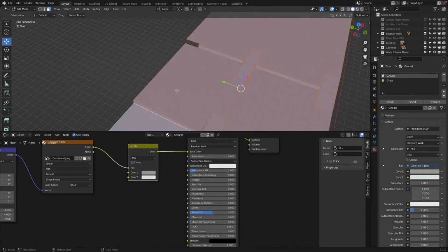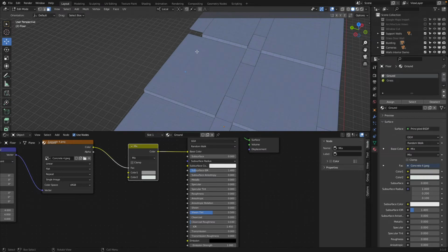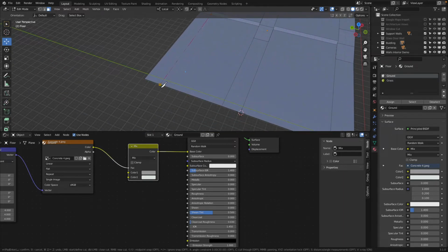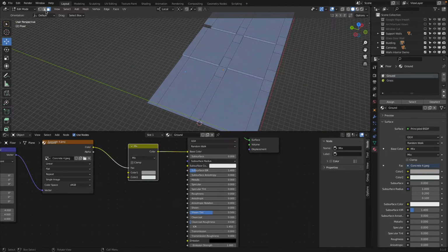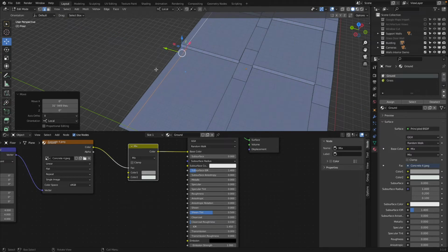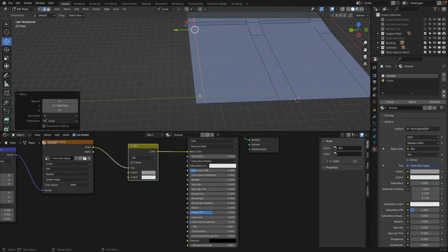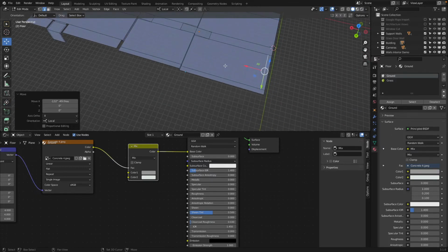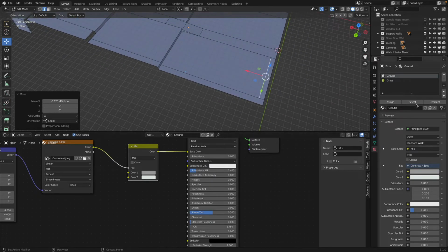So I will AA, there we are, K, click, and click and enter. So then these lines, I will select S, Y, and 0 and scale them so they're nice and tight. There we are. And then here, K, Y, click and enter. And then this line I will drag down. So there might be a few things that have maybe changed.